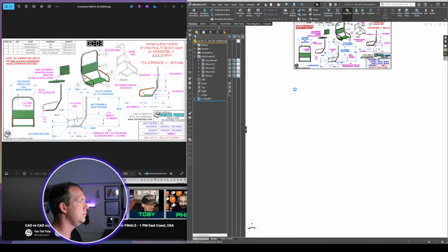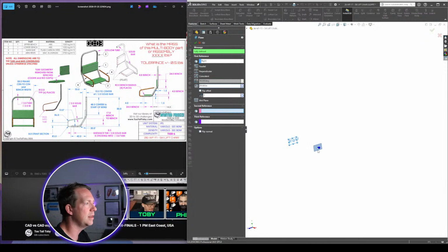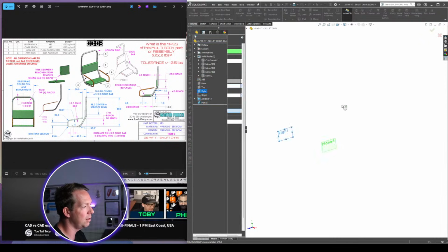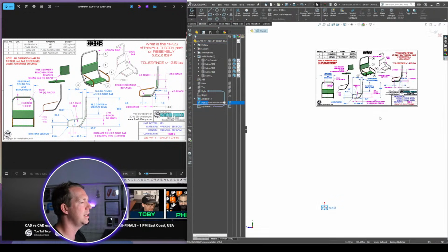Okay, so we're going to start with this one on the right plane. Now, one thing you can do, which can make things easier to do, like the round sweep, is to start with one plane that comes off to the side to get the frame center. So that's a 29 inch offset. And then that's the plane that we're going to start our sketch on.